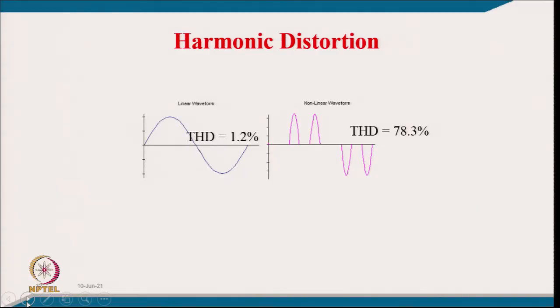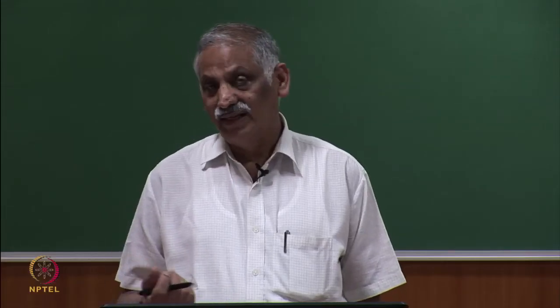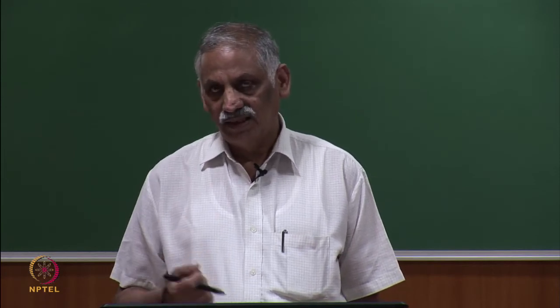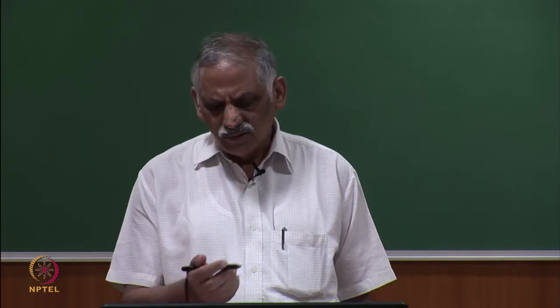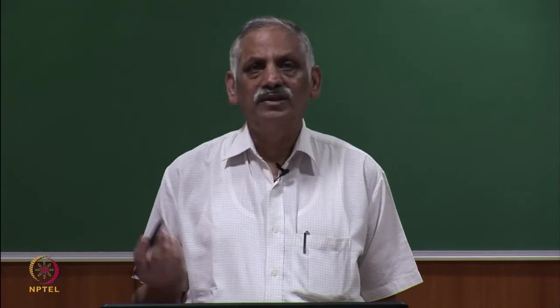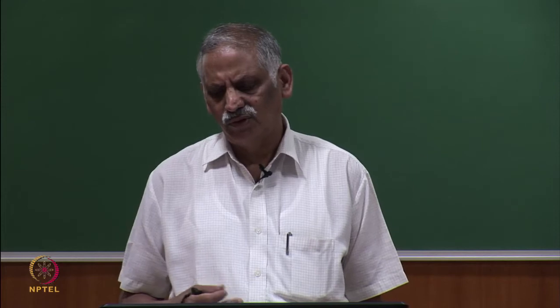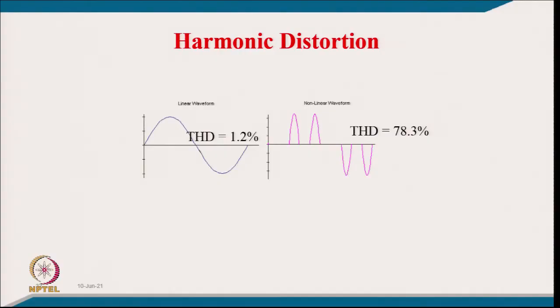If the capacitor is high, then it will certainly suck the energy very quickly from the 3-phase mains, and you will get this kind of wave. But if the load is more and the capacitor is less, then the middle notch can be reduced. You can understand with this practical waveform that the total harmonic distortion of this current waveform is around 78.3%.